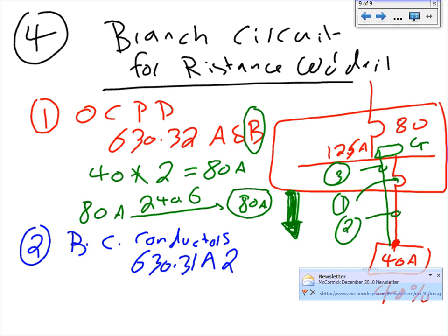There are many ways of doing it. I want you to look at A2. If you look at A2, the ampacity of the supply conductor for the welder, for a specific operation for which the actual primary current and the duty cycle are known, shall not be less than the product of the actual primary current and the multiplier. Under number two, if number one applies to you, if you have the value for number one, you use number one. We don't know anything about that; all we know is the duty cycle here.